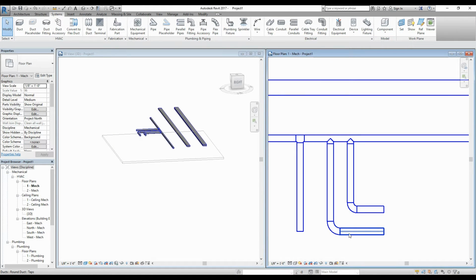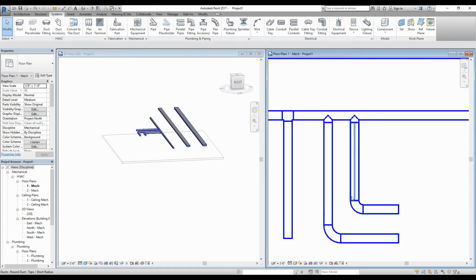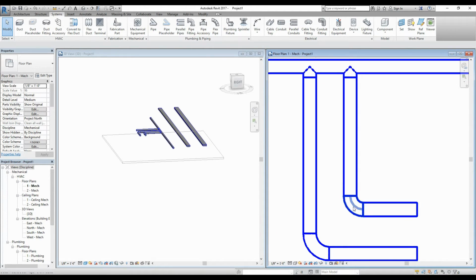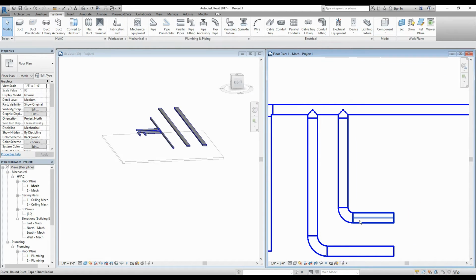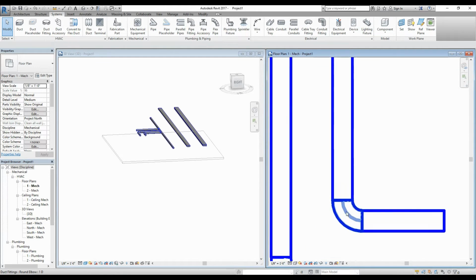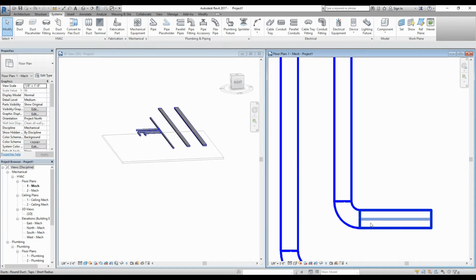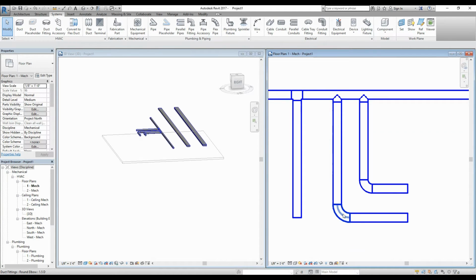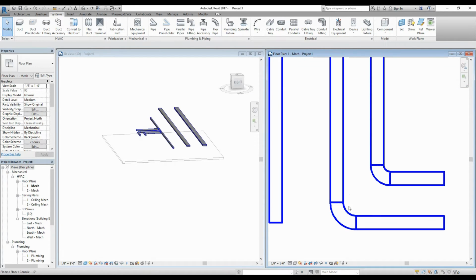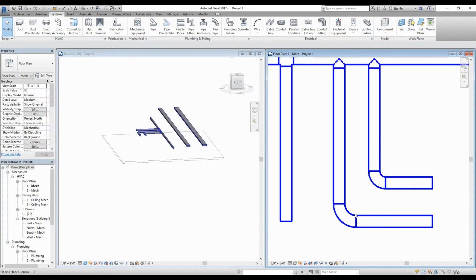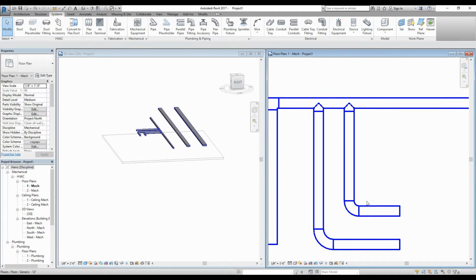This is useful if you mostly want the 1 diameter elbows and not the 1.5, if you're working in tight quarters or in areas where you need only 1 diameter. The 1.5 diameter elbow obviously has less friction loss. So if your company or you're used to using the 1.5 diameter, I would stick with that.